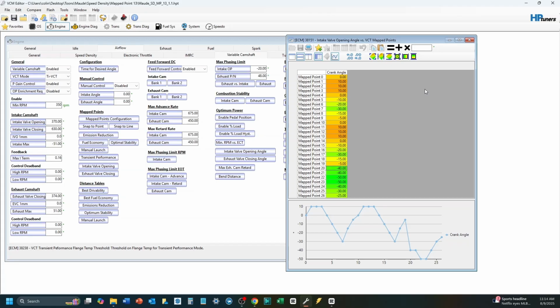This is big partial throttle acceleration. And so we don't need to drive around town as much. This is where we would just do a couple of WOT pulls. And if everything's looking good, right, circle in on it like before, adding 0.5%. And then you've got your high end done.